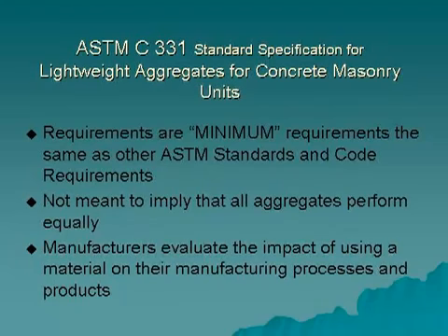As discussed earlier, ASTM C331 presents minimum requirements. These requirements are not meant to imply that all aggregates perform equally. For example, some pumices may meet the minimum standards, but some may not due to the inherent variability of natural lightweight aggregates. Some may qualify as good lightweight aggregates for insulating fill or fill concretes, as previously demonstrated, but not perform adequately as a structural grade aggregate used in structural grade concrete. The same can be said of industrial byproducts when used as a lightweight aggregate.